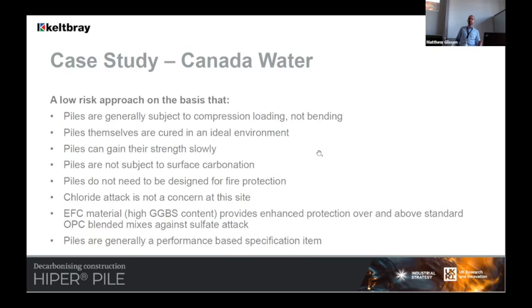And as luck would have it, because of the high GGBS quantities associated with the mix design itself, that actually provides enhanced protection over standard OPC-based mixes against sulfate attacks. So to coin a better phrase in terms of ticks, we were tick, tick, tick all the way down. And as a foundation contractor, we were generally a performance-based specification item.